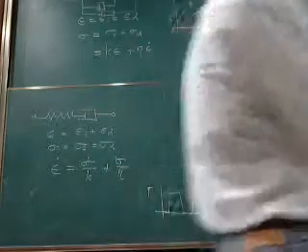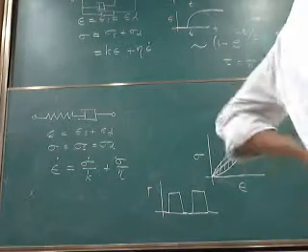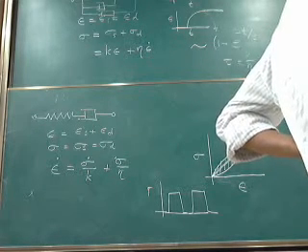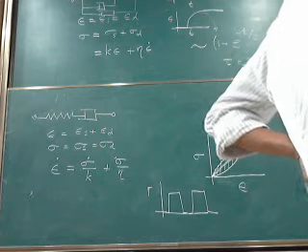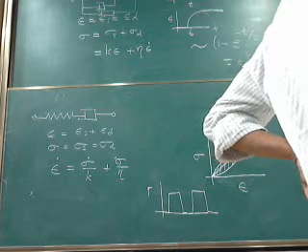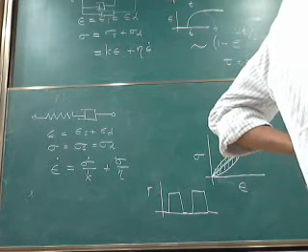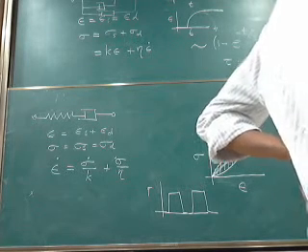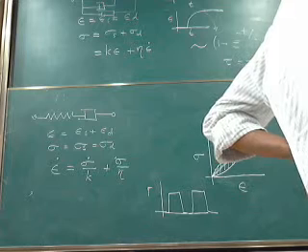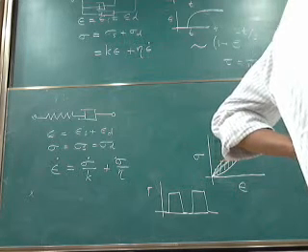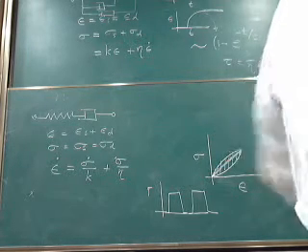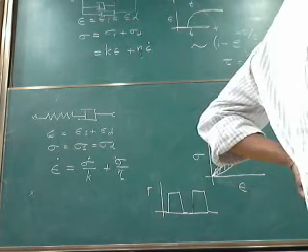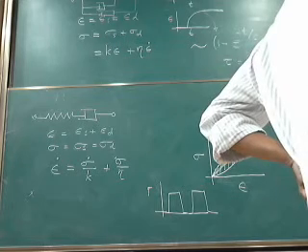So I can just qualitatively explain these equations. At a very short time, as soon as I apply the force, this spring is going to stretch instantaneously. So there is a jump here. You can see there is a jump. Subsequently, this system is going to relax, exponentially, like I mentioned earlier. So this gives rise to an exponential relaxation, and this element, which is in series, gives rise to a continuous strain. So continuous straining of the material,